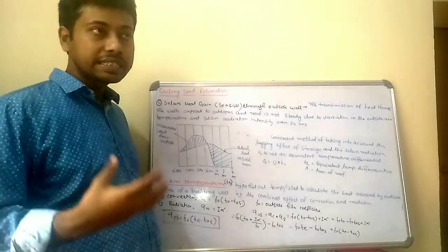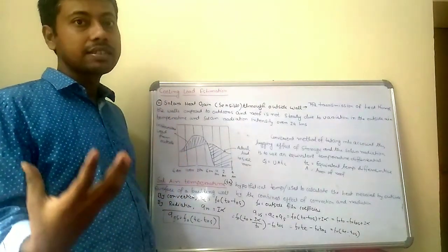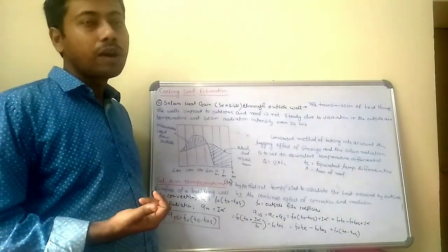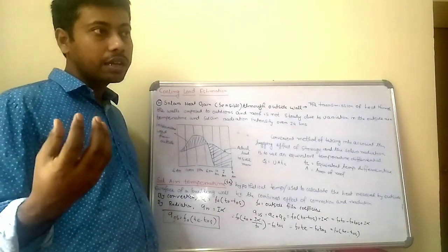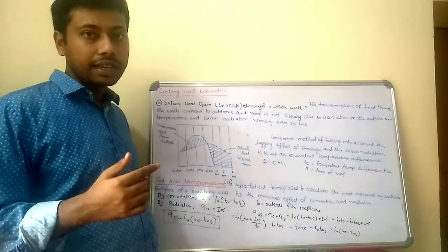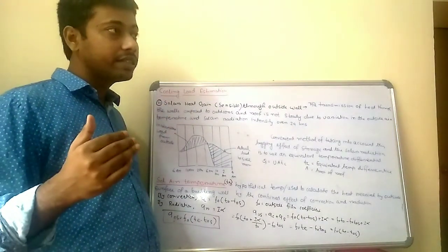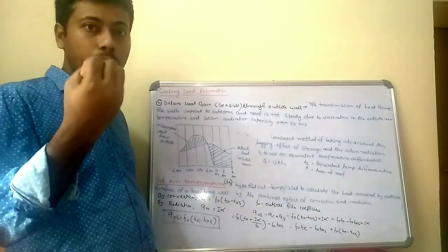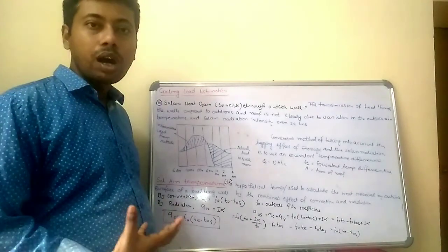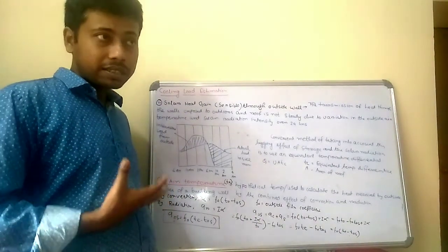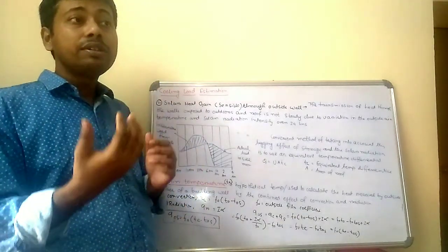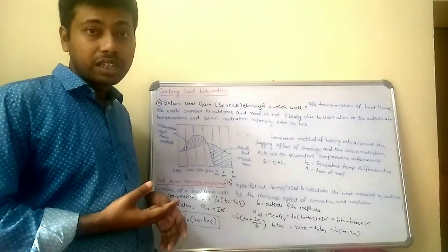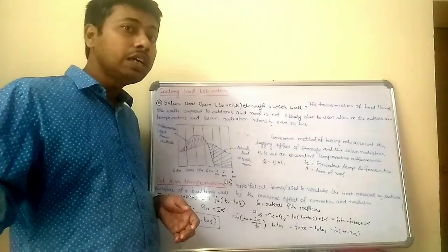It depends on the intensity of the solar radiation and the direction from which it comes and falls upon your roof or outside walls. If the radiation falls at a high angle upon your wall or roof, the amount of heat absorbed by the wall or roof is obviously very high. But at that particular time, they just absorb, not release. After some time, in the evening part of the day, they release the heat into the room.